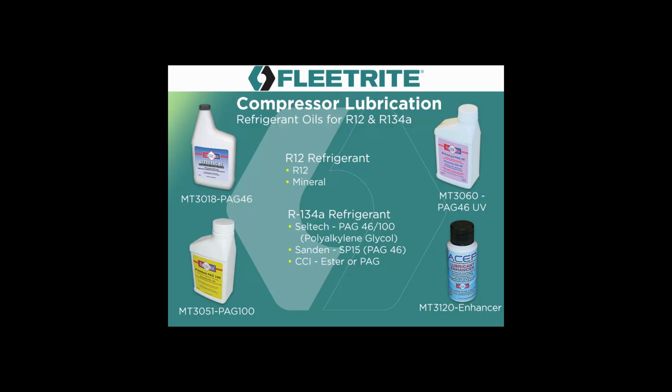As time has gone on, that viscosity number has gone down, where most manufacturers today are recommending and using generally a PAG 46 or a PAG 100, a little lighter weight oil, because even in the wintertime, when you run your defrosters, you're still running your AC compressor, so you need a lighter weight oil that flows well, that will still lubricate that compressor even when it's cold.